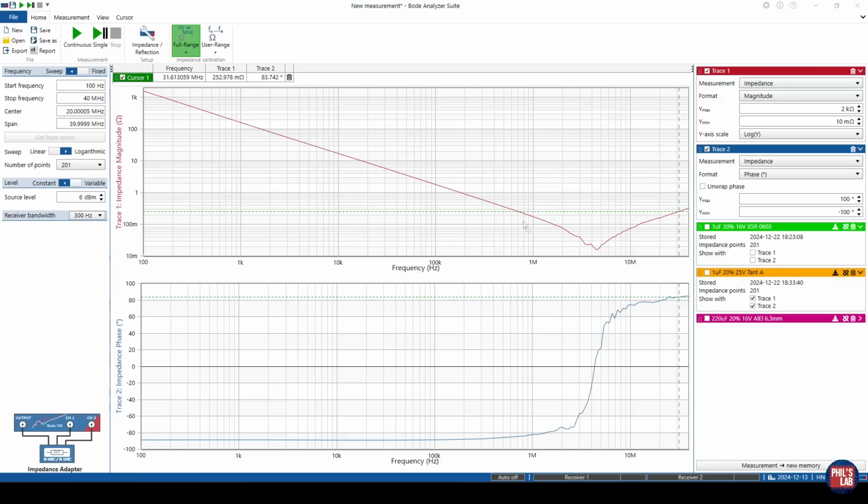As well as a certain DC bias, maybe 3.3 volts, maybe 10 volts, maybe a certain ambient temperature, that will all change these parameters that you're extracting. So we are creating a model now at a single operating point. And that is valid for that operating point only, but for many circuits it's a good overall approximation for a more broadband behavior. I'll show you how to do this very, very generally.